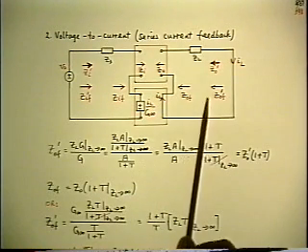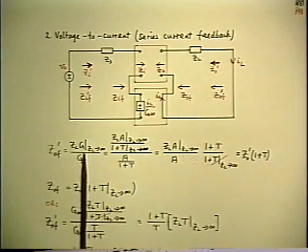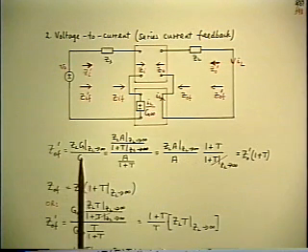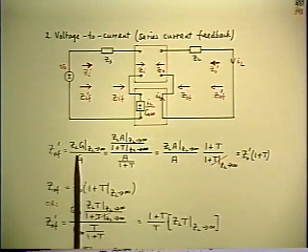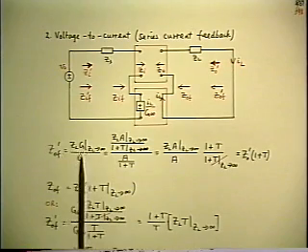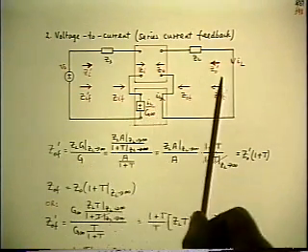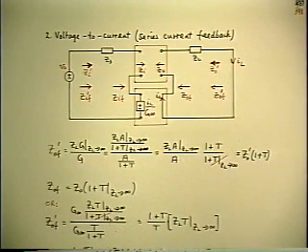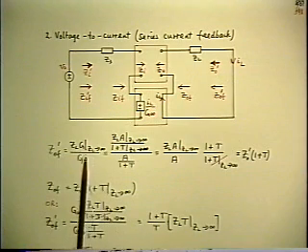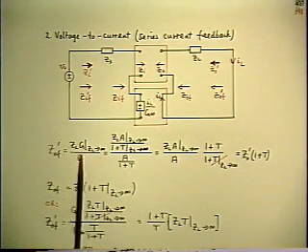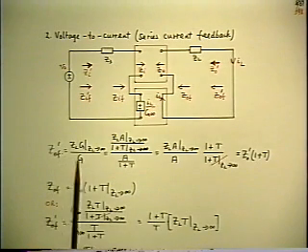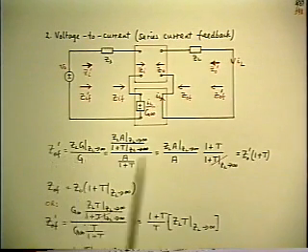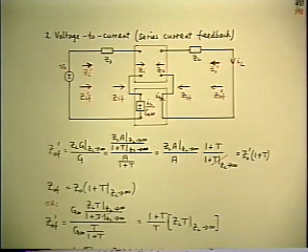So all you have to do is take the same formula that we already have for input impedance and substitute the subscript ZL instead of ZS. Because clearly, since the configuration is the same, the algebra will be the same as well. So the formula for the output impedance is the same as it is for input impedance, except for ZL in place of ZS for this configuration.